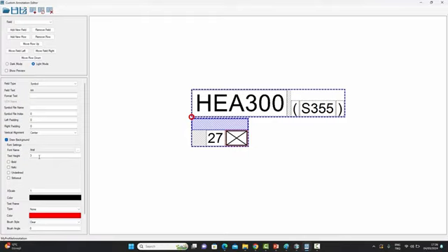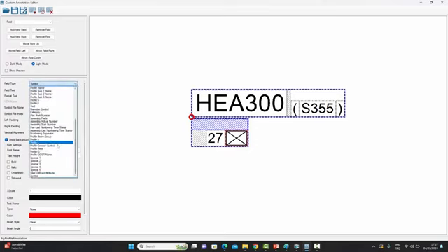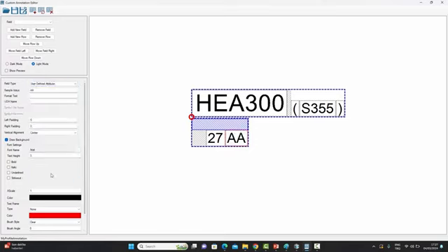So as you can see, this custom annotation is extremely powerful. It allows me to create up to 3 lines. Each line can have as many components as I want. Each component can either be an intelligent field, it could be a text, it could be a symbol, or it could even be a user-defined attribute. So for example, instead of the symbol, if we come down over here, there's a user-defined attribute as well. And in that case, you give the UDA name, which we discussed in the beginning. And whatever UDA name you give, if this object has that, it will create that when creating the annotation. So it's a very powerful new technique. You can create these totally customized annotations.